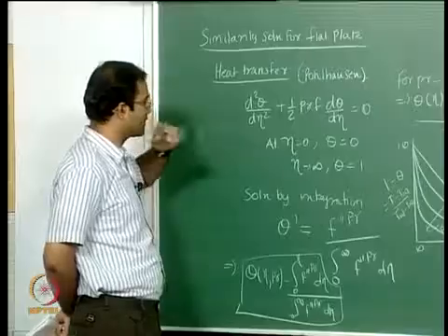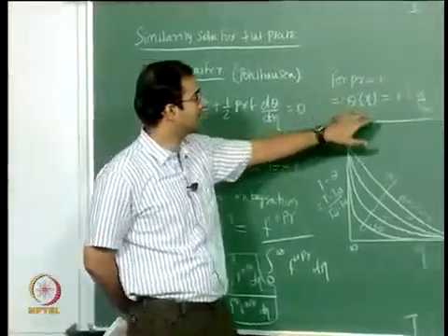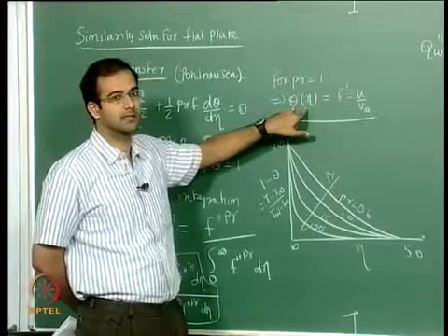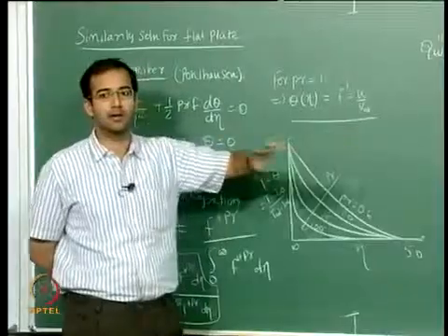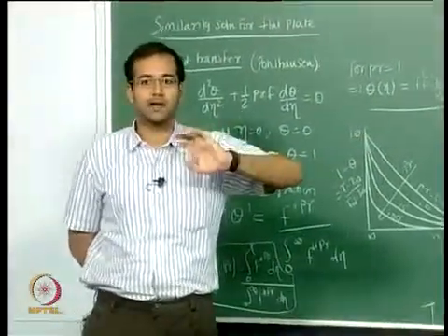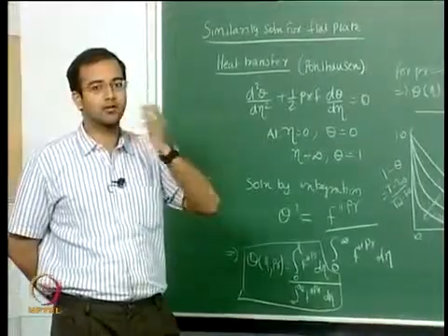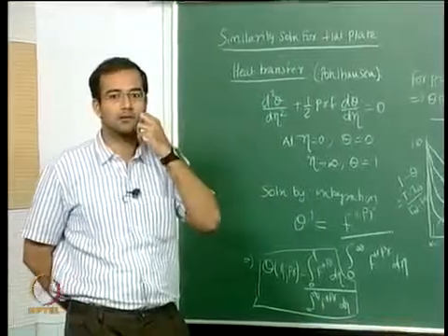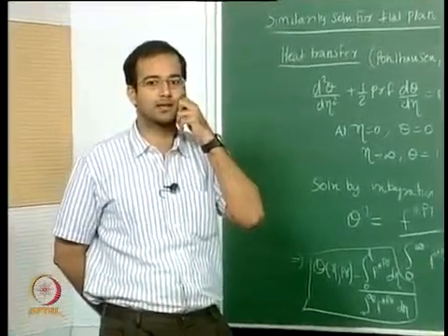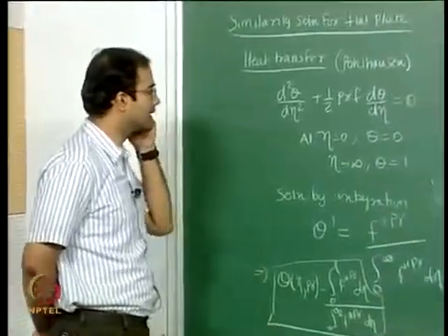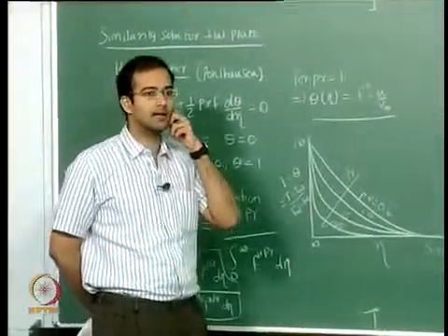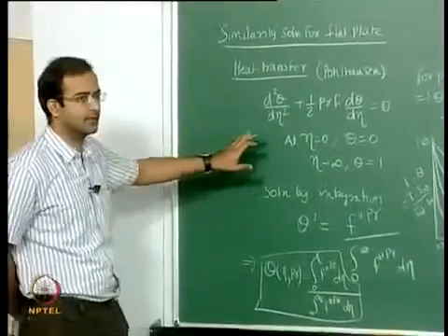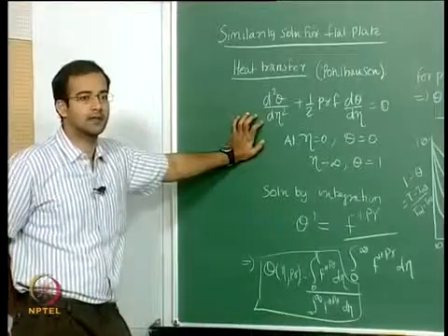And of course, you know, from the intuition that for Prandtl number equal to 1, if you replace the temperature variable, non-dimensional temperature theta, with the non-dimensional velocity, the momentum and the temperature equations are identical exactly. So Pohlhausen got the idea that if for Prandtl number equal to 1, they have the same solution, so for other Prandtl numbers there should be some kind of a similarity solution possible. So then he intuitively substituted the same similarity variable which was used for velocity boundary layer, and finally he finds that this falls into the category of similarity solutions.